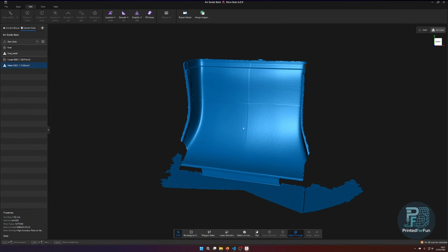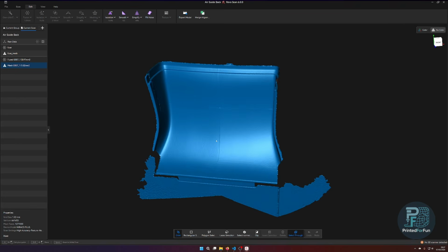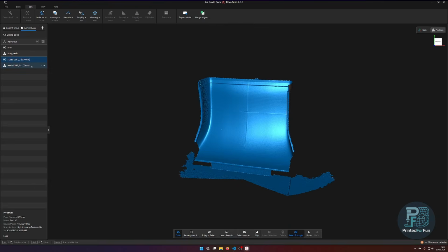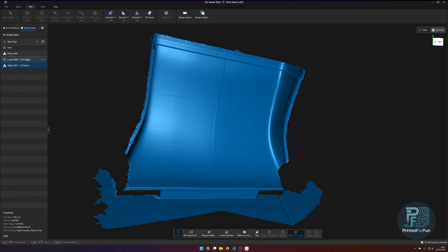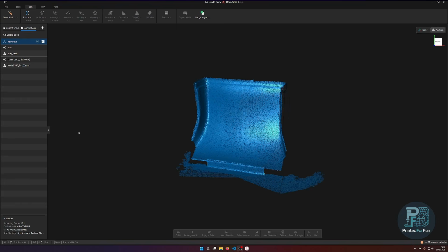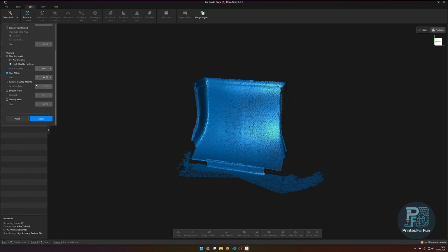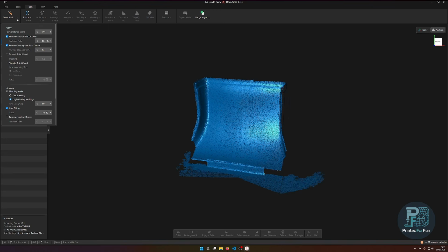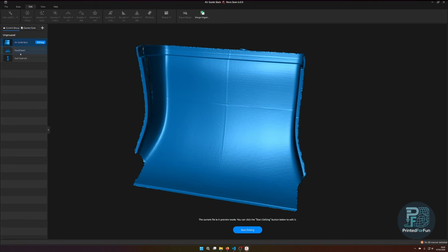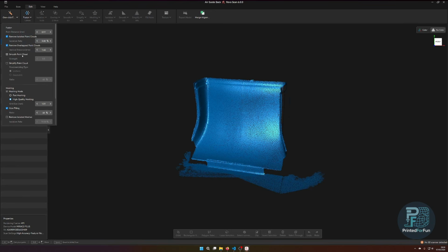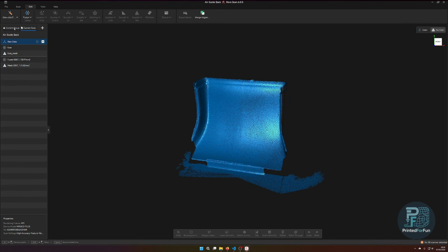So the one-click editing is now run through. And what you're seeing for the Fusion and for the mesh, it also directly tells me what settings were used. So if I go now back to the one-click edit settings, you can see it saved the settings. So if I have multiple scans here in my group, like here, I can now go to the next one and directly remesh again with the same settings.